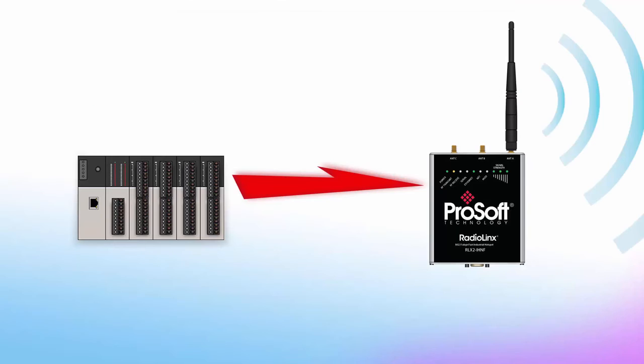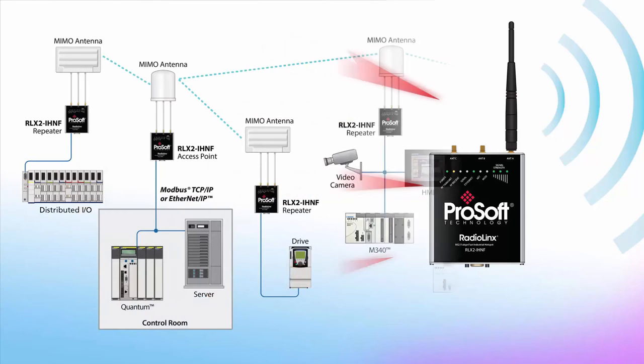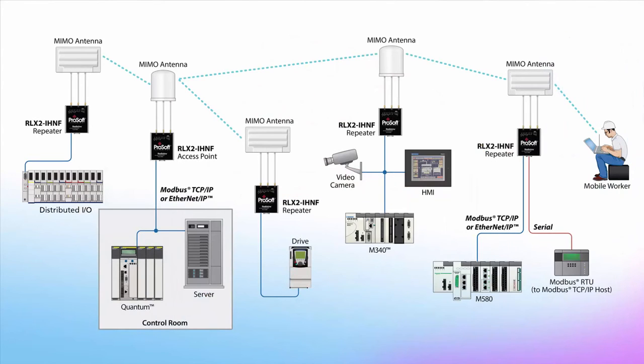It's also possible that the data rate is simply too fast, and the radios cannot keep up with the RPI your devices are configured for. Make sure that RPI settings for your equipment are set no faster than what is actually required for your application. Those are the most common solutions to the problems we typically hear about.